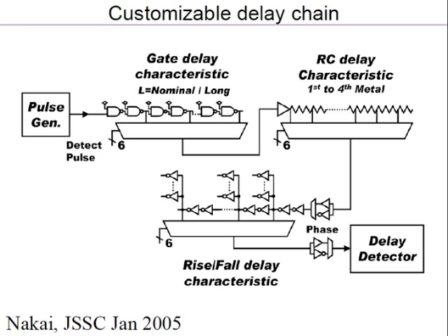Okay, so if you want a good model of a critical path, remember when I say model here, the model is also in silicon. It is not the mathematical model which is there only during design time. It is a small piece of circuitry which is modeling some other bigger piece of circuitry. Some characteristic of the bigger piece of circuitry is being modeled by the smaller piece of circuitry. The smaller circuitry you have made because it's easy to measure it.